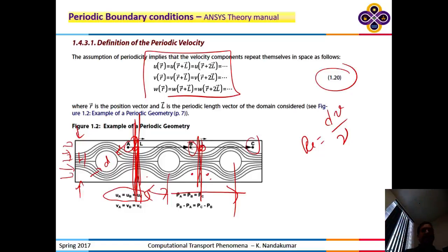So if you look at the entrance length information, we say, for example, for the flow to develop along the length of a channel, I need 10 widths. Then you would use the width as your scale to calculate the Reynolds number. But if you're interested in the wake that forms behind these cylinders, and you want to understand the wake dynamics, then you would use d, the diameter, as the characteristic length for your Reynolds number.